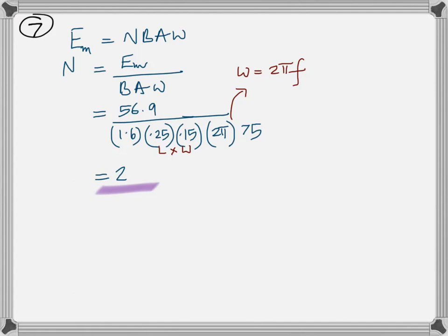Okay, but when it begins operation, what would be the current? What's the back EMF when it begins operation? Just when you switch it on, what's the back EMF? 0. So that means you have the entire 120 volts divided by 6, which is 20 ampere. That is dangerous. Because like I told you before, the insulation is microscopic, it's going to burn out now. If you let that 20 ampere flow even for a few seconds, you lost the motor. So what do you have to do for any motor?